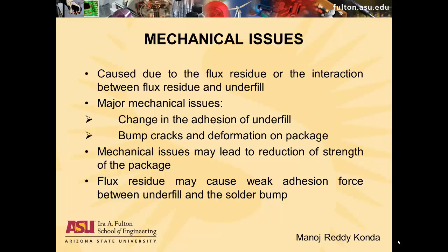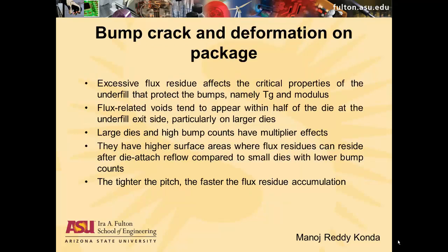These issues may lead to reduction in the strength of the package and may eventually lead to the failure of the package. In this slide, we are going to see how the bump cracks are caused. As we have seen earlier, excessive flux residue affects the critical properties of the underfill that protects the bump, namely the glass transition temperature and the coefficient of thermal expansion.